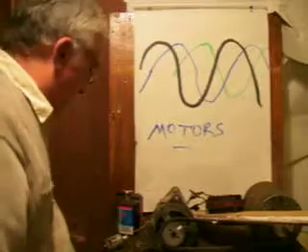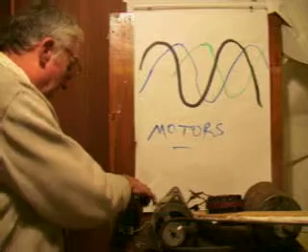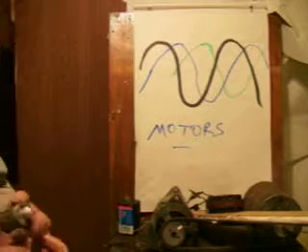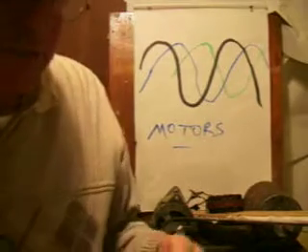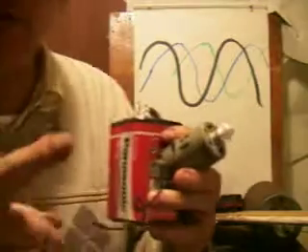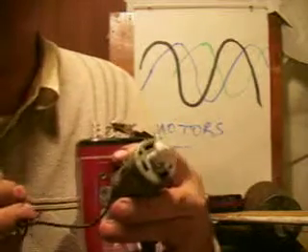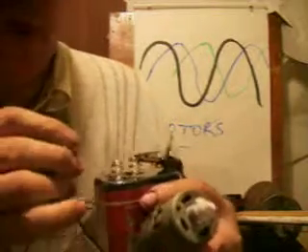But one of the problems with such a motor, which was self-starting, was that there was no connection between the generator's speed and the actual motor's speed. So if you used them for something like an elevator in a shopping centre, you couldn't control the speed. The speed was a function of the load and the power in.